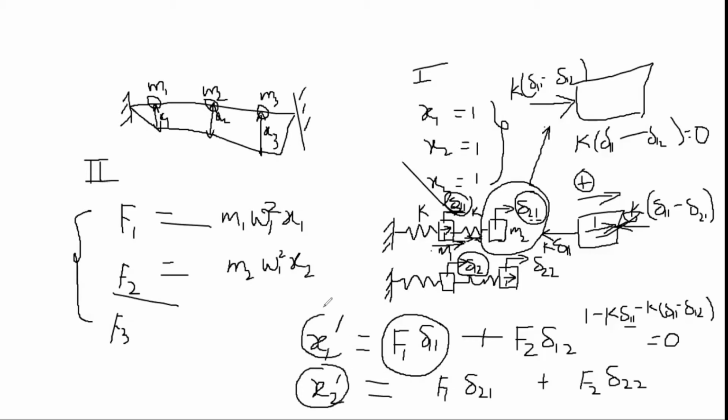Okay. So what we are going to do is that we started with initial values of deflection, assuming initial values of deflection, then calculating the inertial forces because of the assumed value of deflection, and finally we come out with the new values of deflection. Now this is step number 1, this is step number 2, this is step number 3.